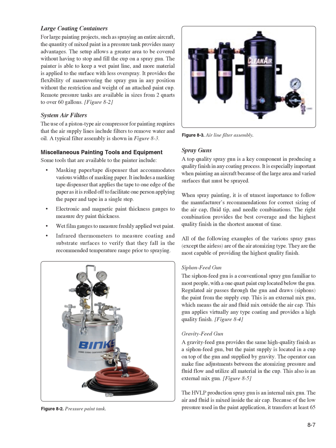Infrared thermometers to measure coating and substrate surfaces to verify that they fall in the recommended temperature range prior to spraying. Spray guns. A top quality spray gun is a key component in producing a quality finish in any coating process. It is especially important when painting an aircraft because of the large area and varied surfaces that must be sprayed. When spray painting, it is of utmost importance to follow the manufacturer's recommendations for correct sizing of the air cap, fluid tip, and needle combinations. The right combination provides the best coverage and the highest quality finish in the shortest amount of time.